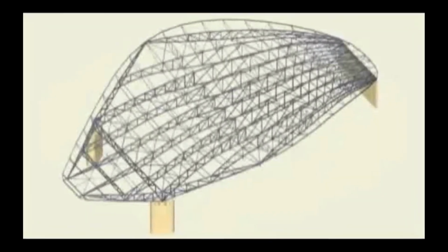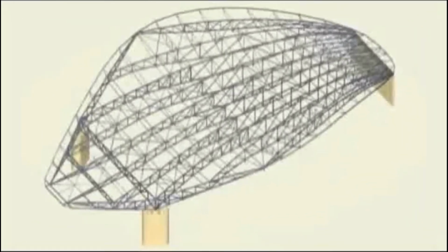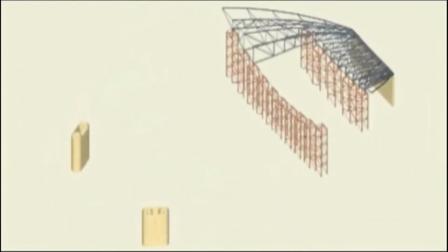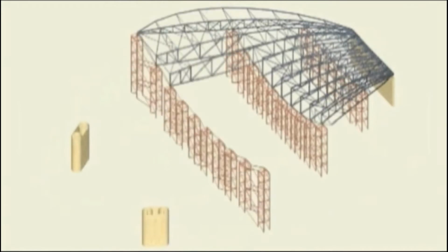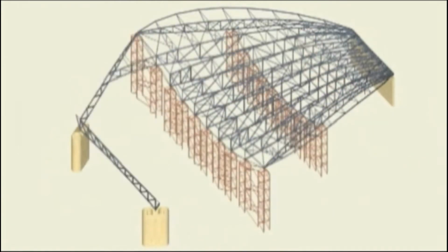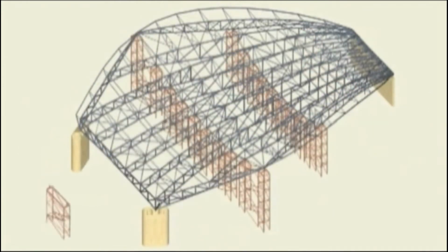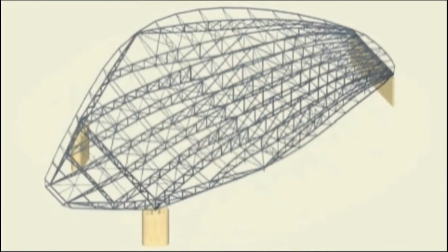And finally, the overall roof construction process was carried out as follows. First, the supports are erected and the trusses are installed, supported by a temporary trestle. After every truss is lifted up, the temporary trestle is removed because deflection can occur in a long span truss.